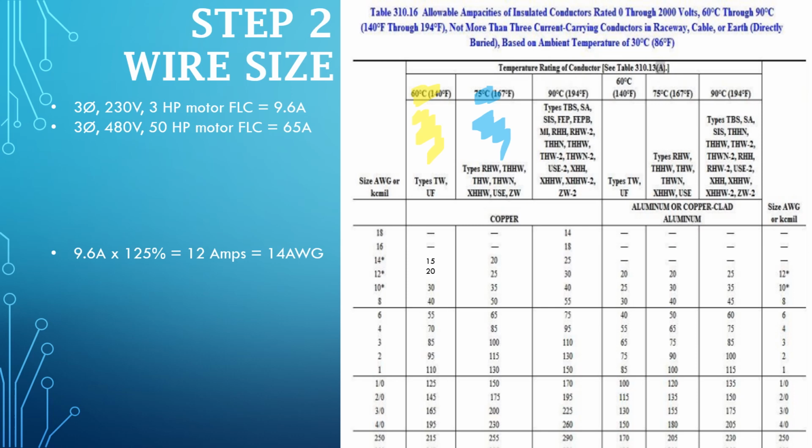And the reason for this is, although we're choosing a wire size based on the insulation and its other properties, we don't know what the terminations for that wire are going to be hooked to. We don't know, is the device that it's hooked to rated for 90 degrees, or is it rated for 75 degrees, or is it rated for 60 degrees? We have to work on the assumption that it may not be. And so if it's less than 100 amps, we use the 60-degree column.